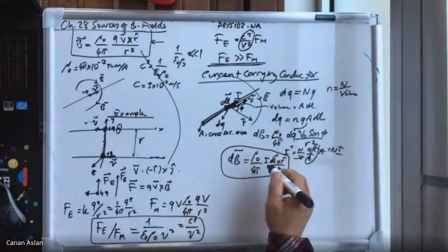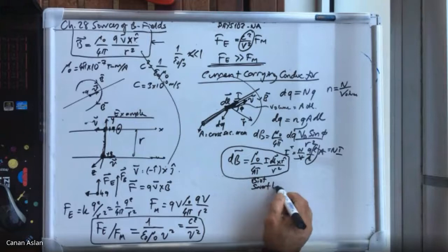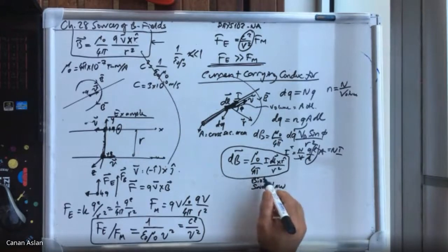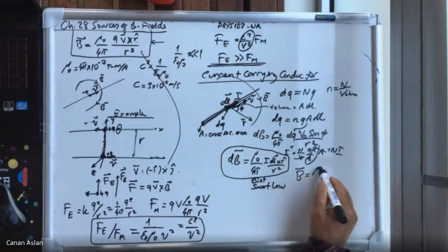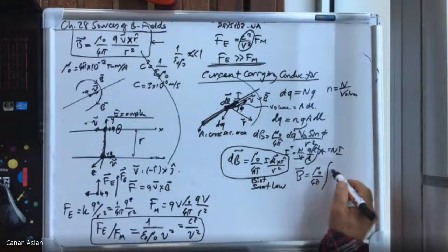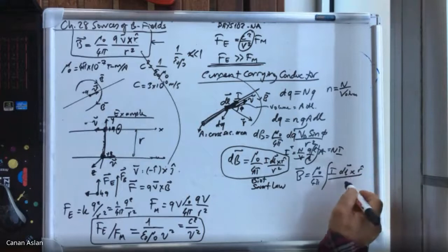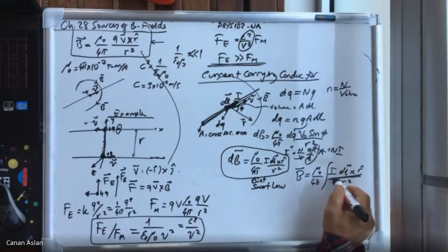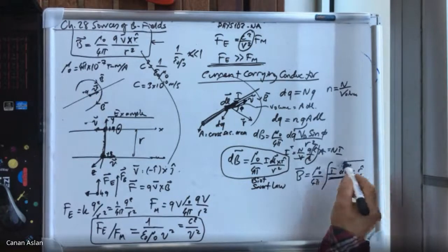So this is the Biot-Savart law. By using the Biot-Savart law, we can calculate the magnetic field using this integral. If you integrate the whole thing, you will get the magnetic field distribution due to current in any direction, and the direction at which the magnetic field is obtained is also arbitrary, given by an arbitrary vector r.